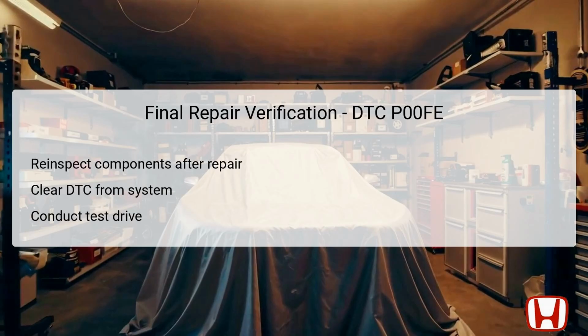Upon completing the necessary repairs for DTC P00FE, it is critical to conduct a final verification of the repairs made. Begin by re-inspecting all the components involved, specifically focusing on the vent line and EVAP canister, to ensure they've been correctly installed and are functioning properly. Once you confirm that no visual issues remain, clear the diagnostic trouble code from the vehicle's onboard computer system using the HDS to reset the system.